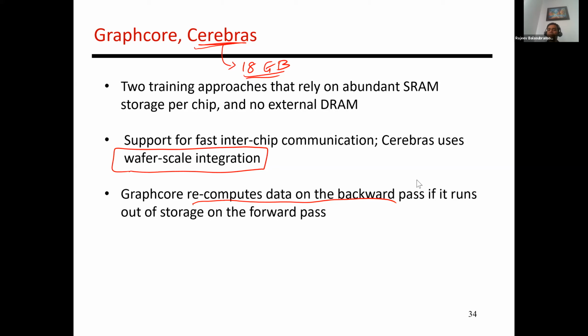Yeah, and so most accelerators for both inference and for training are gravitating towards 16 bits. Inference accelerators can also do 8 bits, and so even the accelerator from Groq, I think, does 8-bit integer arithmetic. But for training, some format using 16 bits is popular. bfloat16 and FlexPoint have received the most attention so far. So hopefully that answers your question.